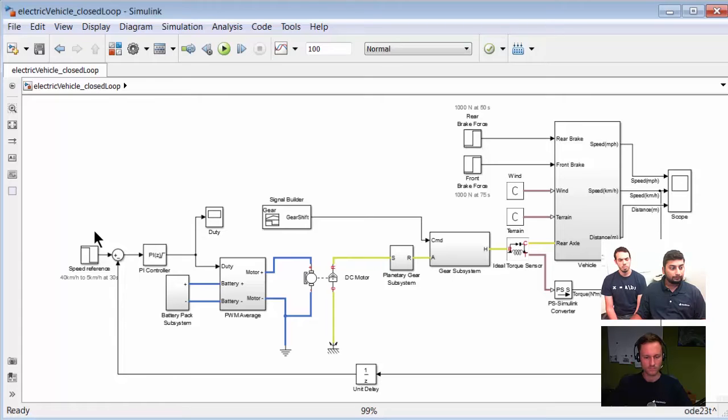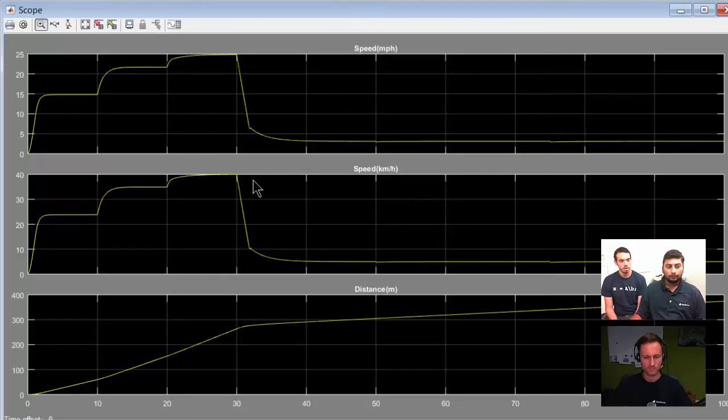That's nice. So why is it then that it looks like the speed reference goes from 40 kilometers per hour down to some value of 5? How come you see other things going on here? Like I see the speed is going up in 3 sequential steps. Yes. So you can see the 40 kilometers per hour to 5 kilometers per hour here, right? Apart from that, you also see these steps, and that's what Sebastian is asking about, and that is the effect of gear changes on the vehicle. So the different gear changes result in the different steps in the speeds here.